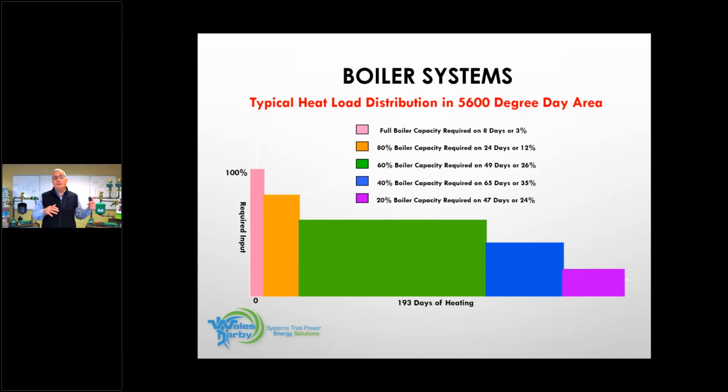Because if the boiler that was there was oversized to begin with, I could take advantage of that and run lower temperature to the existing baseboard and offer Mr. Smith more options. I can offer them a condensing option and make more money, or offer them a properly sized cast iron, still with the outdoor reset, make more money, or just offer them plain Jane properly sized cast iron boiler. We do a whole class on selling, and the more options you have, the more chances you have to make more profit. All right.